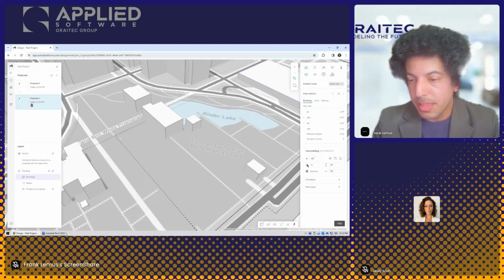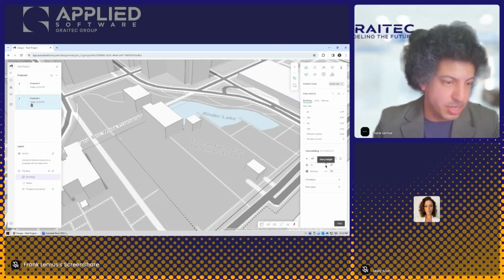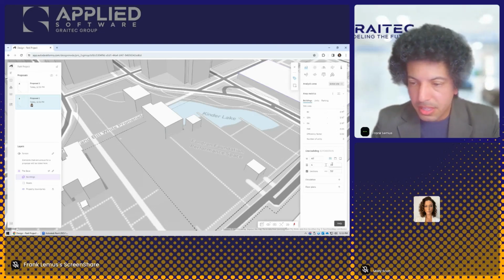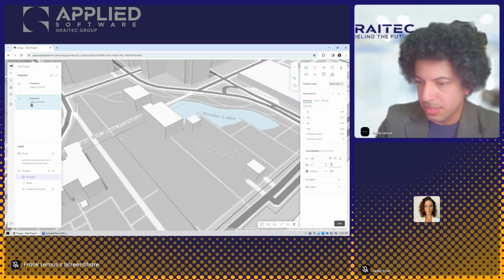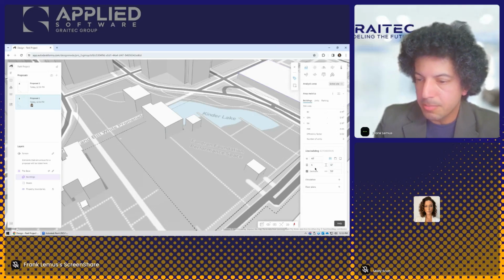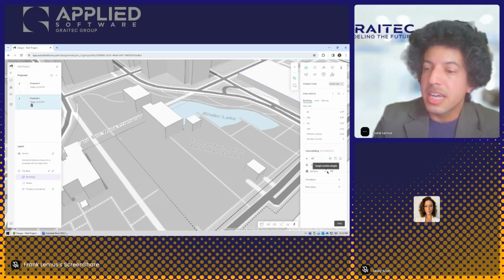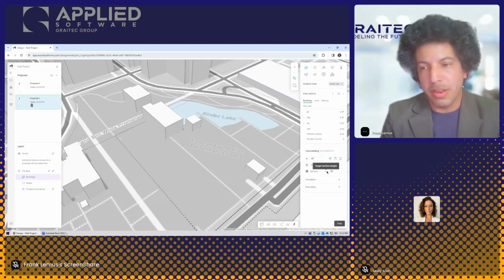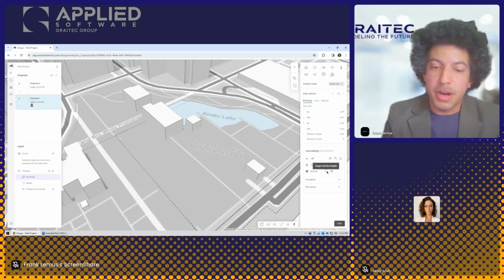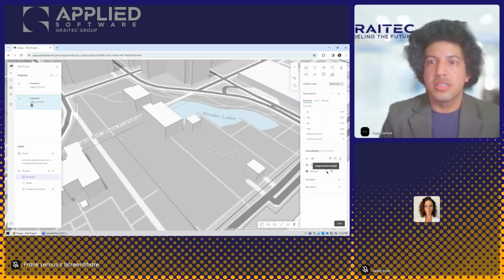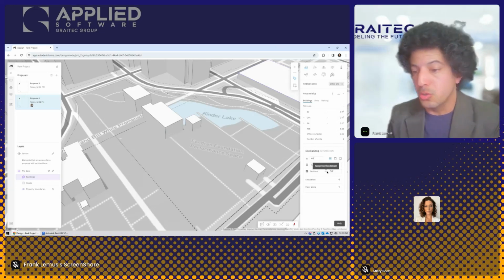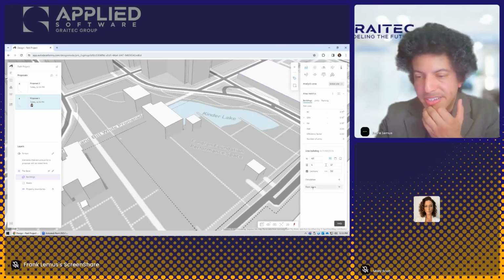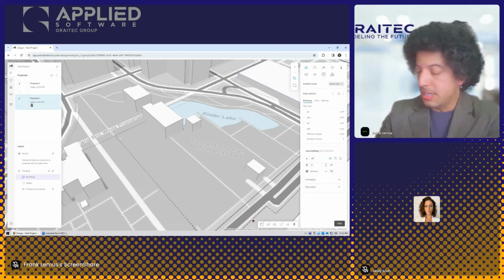See, you've got the width, you've got the number of floors. These are all defaults that I'm setting right now, but of course I can change them later. The story height, I usually like to say 12. That's a little bit more realistic, I think. And the section length. In other words, how often will Forma break the model to subdivide it as an individual unit? Okay, and we're going to look at circulation and floor plans in a second.